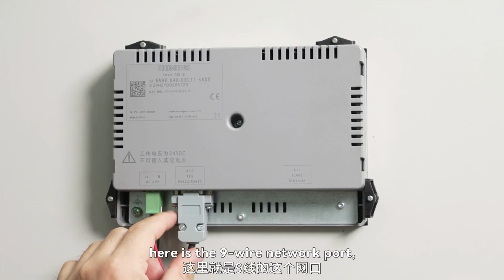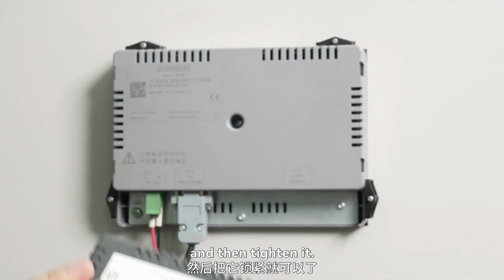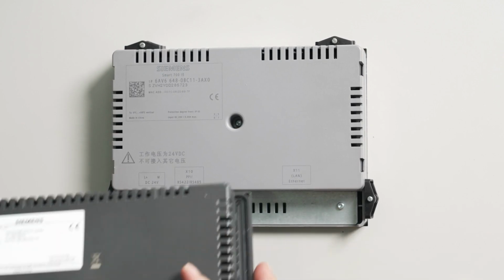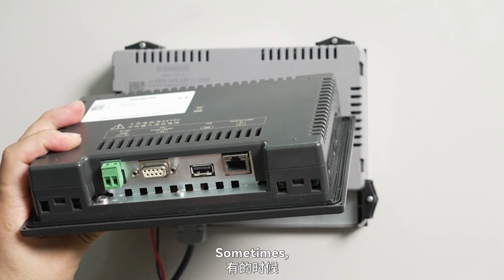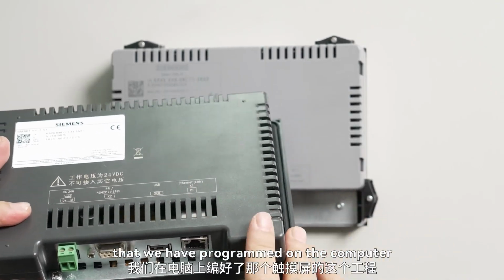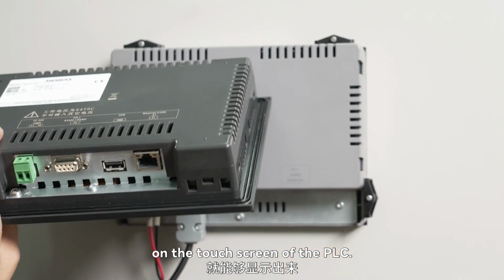Then the second one, here is the 9-pin port, the signal line from the PLC. Just plug it in, loosen it with that, and then tighten it. The third one is the network port. Just plug the network cable in here to achieve communication. Sometimes we need to connect this network cable. After powering on, transfer the project of the touchscreen that we have programmed on the computer to the touchscreen of the PLC, and then the content can be displayed on the touchscreen of the PLC.